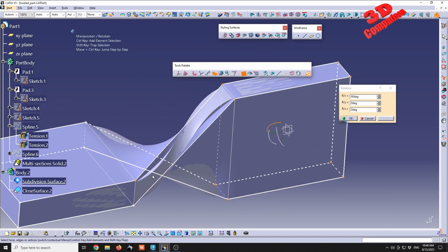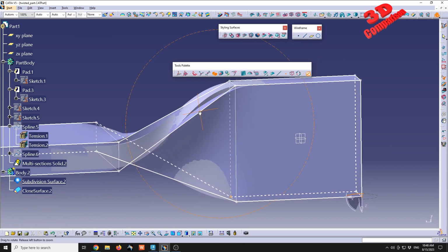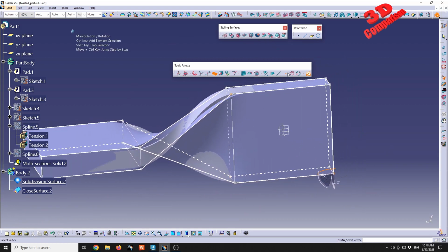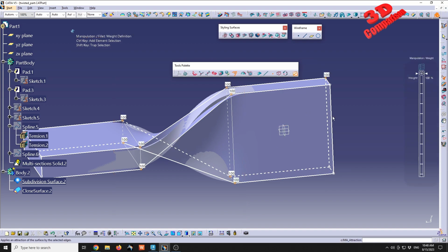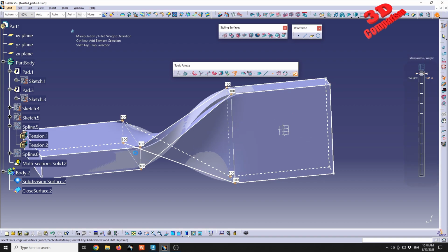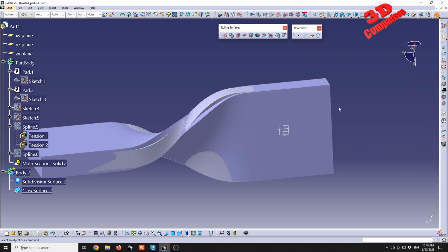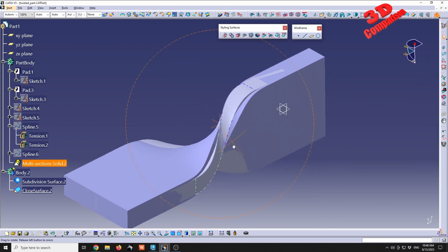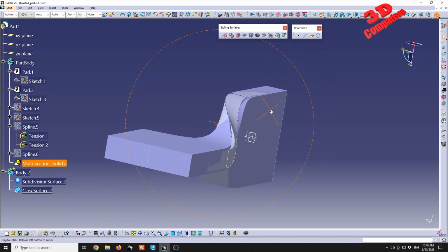And as we can see, that twist can now be influenced by the attraction. So select all the middle points, go to the attraction, and according to that weight we can further increase that. But it's still not the same spline that defines that. So we can further rotate and adjust that.